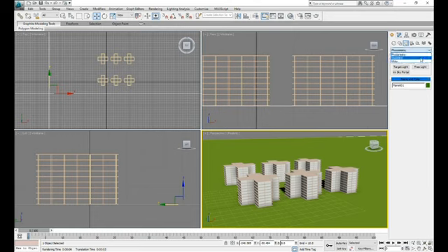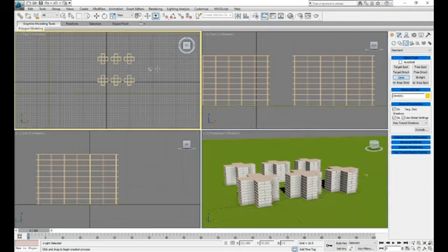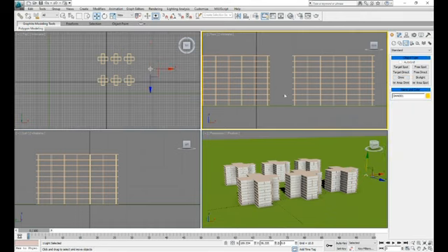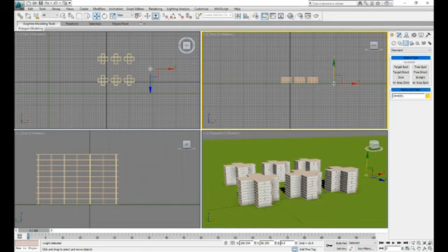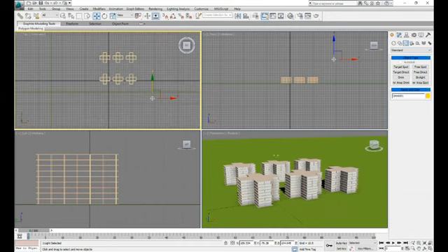So I will go for standard. I will click Omni. Now make sure this Omni light you just click once when you put it at the top. Once only. Click, right click. You can see now the Y and the red if you right click that one. So I will go up, put it here. So this is my shadow now.